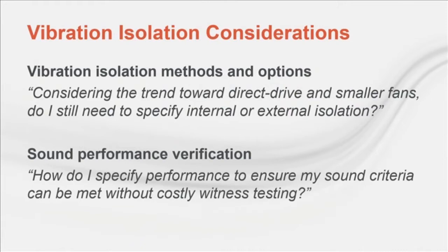To help make the best decision on which isolation method to choose, be sure to request quality sound data taken in accordance with ASHRAE Standard 260. Then simply compare the unit sound power levels with the job requirements. Note that it's not as easy as simply removing the isolation hardware and retesting. A unit designed for a particular isolation method must have had any issues encountered evaluated to ensure smooth performance, both acoustic and vibration, throughout the operating range.